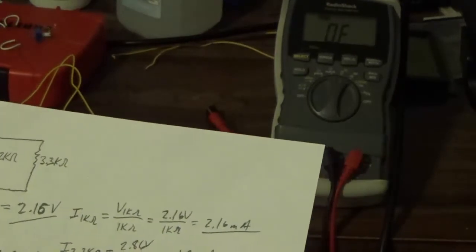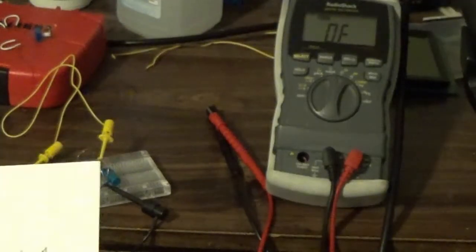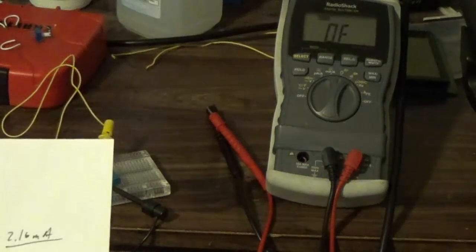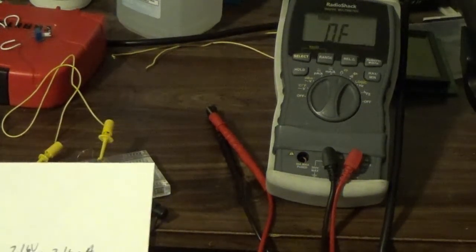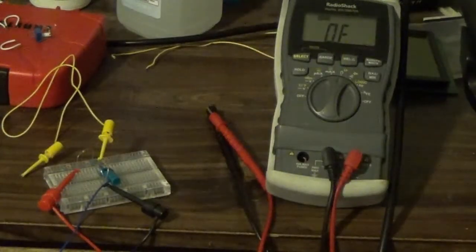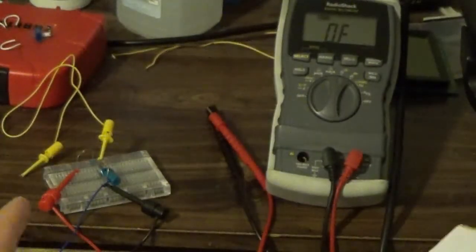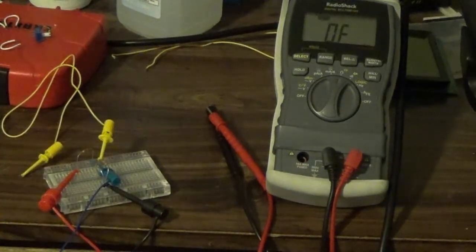Why they do that is because if somebody wants to drive this thing at a higher voltage, maybe to get a better, stronger signal out, so they want to drive it at 5.5 volts or something, and if their power supply all of a sudden decides it wants to be, if they read out 5, but they're outputting 6, or they're outputting 5.7 or 5.8, that extra padding needs to be there in order for them not to blow their circuit up or blow their IC up, because it's not, well, I shouldn't say it's not fun blowing stuff up, because I like blowing stuff up myself.